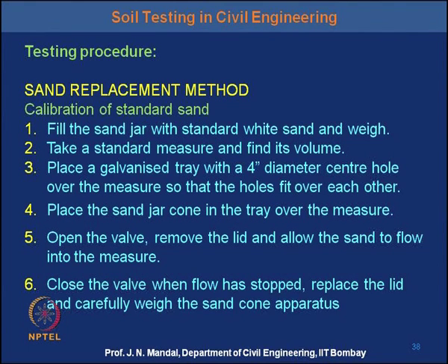So, what is the testing procedure? First of all, in the sand replacement method, you require calibration of the standard sand. Fill the sand jar with the standard white sand and then weigh it. I have shown you what the white standard sand is. So, you fill it into the jar and take the weight of that white sand. Take a standard measure and you can find its volume.